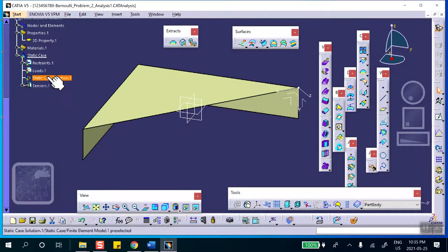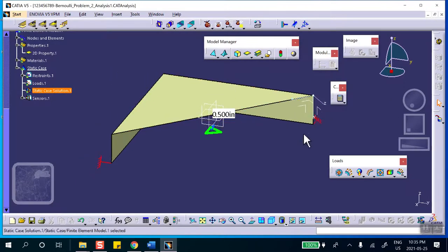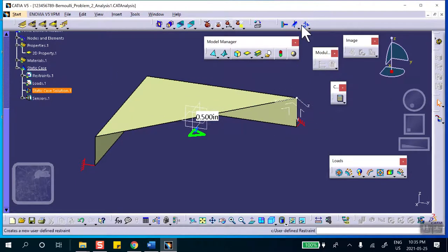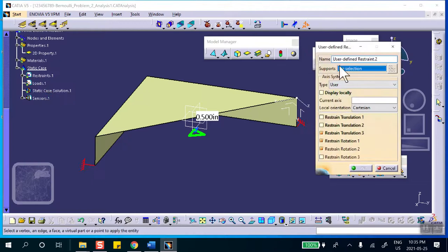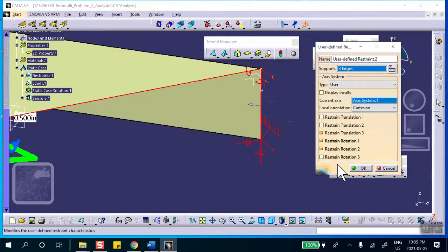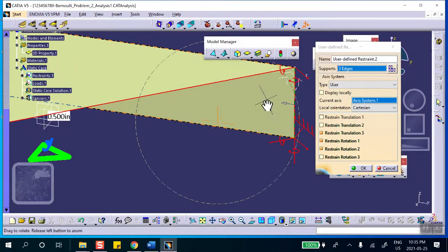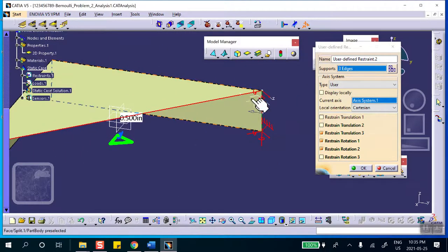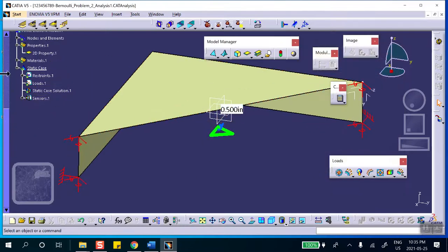So let's go back to the FEA. All the stuff that gave me a hassle, it didn't work. Now we're going to fix it. So user coordinate system is this, there, okay? And these three edges are here and there and there, okay? Remember that in that coordinate system, these three edges that I picked lie in the XY plane, therefore there is no displacement in Z, and rotations are exactly the opposite. No mistake here. There. You see, there is no exclamation mark there anymore.